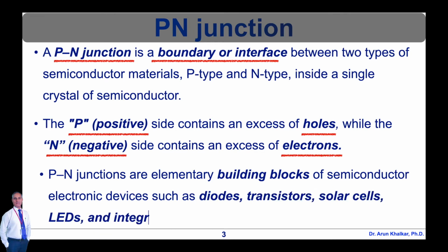The p-n junction is created by doping, for example, by ion implantation, diffusion of dopants, or by epitaxy, that is, growing a layer of crystal doped with one type of dopant on top of a layer of crystal doped with another type of dopant. If two separate pieces of material were used, this would introduce a grain boundary between the semiconductors that would severely inhibit its utility by scattering the electrons and holes. The detail about this we will discuss in the last unit, that is, physics of nanoparticles.